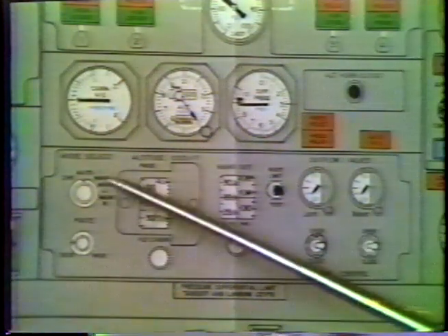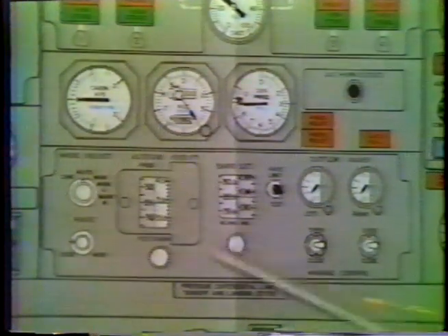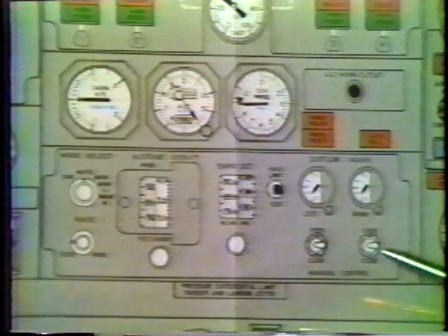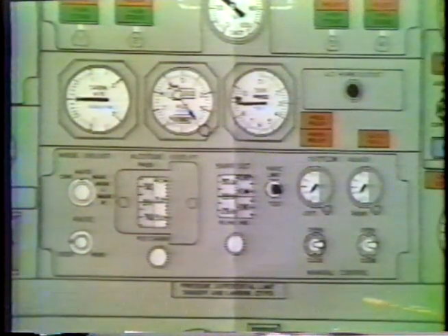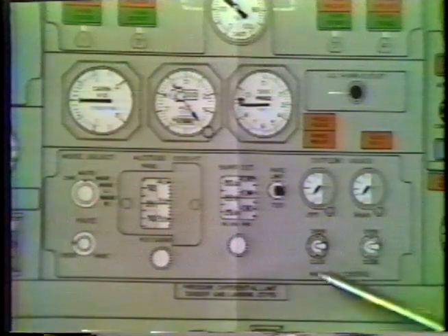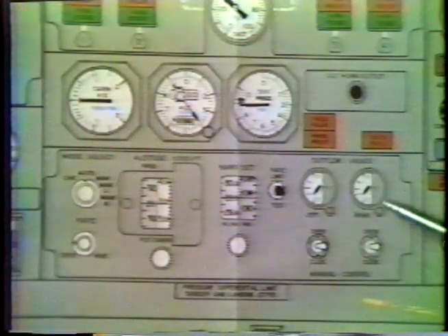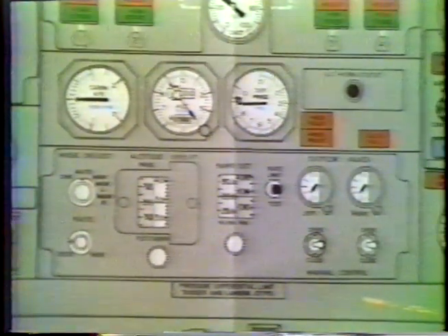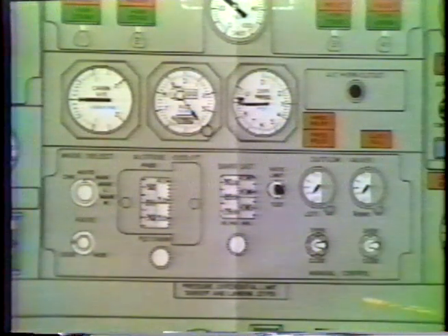The difference between manual and manual left and manual right is when you go to, for example, manual left, the left outflow valve is under control of the toggle switch. The right outflow valve is still under control of the auto controller. The advantage of this is if something is wrong with the auto controller on the left outflow valve, you can toggle the left outflow valve to approximately 1/8 from full closed and allow automatic operation on the right outflow valve for climb, cruise, descent, landing, etc. And it will do a good job. You don't have to sit there and control the rate of descent with the outflow valve.